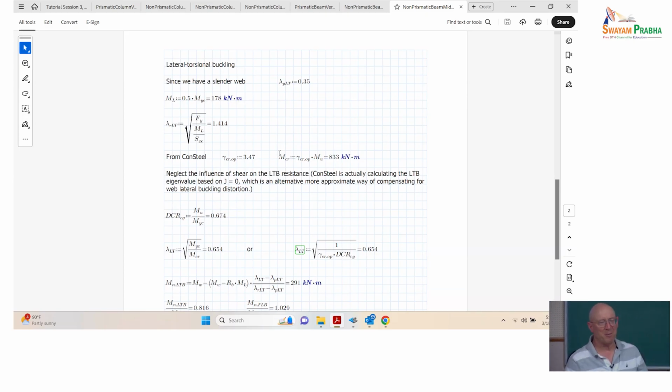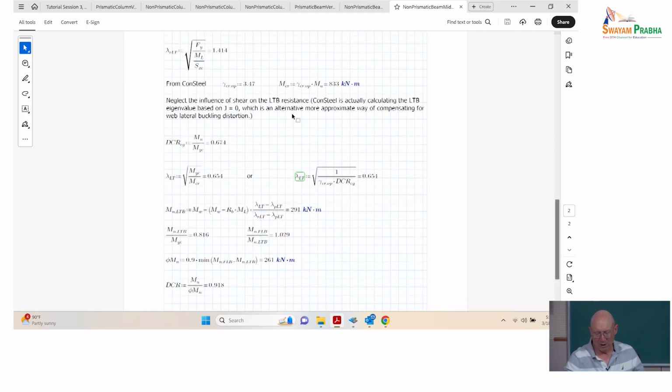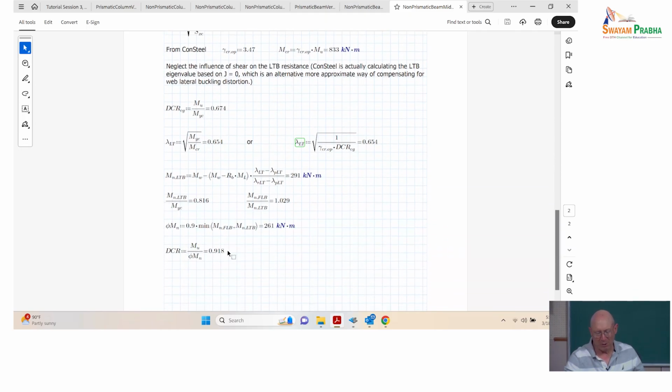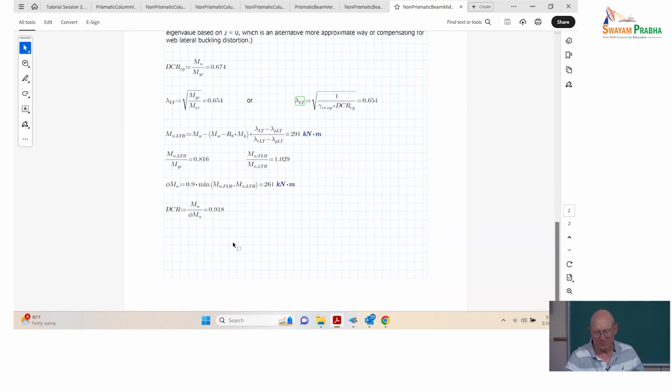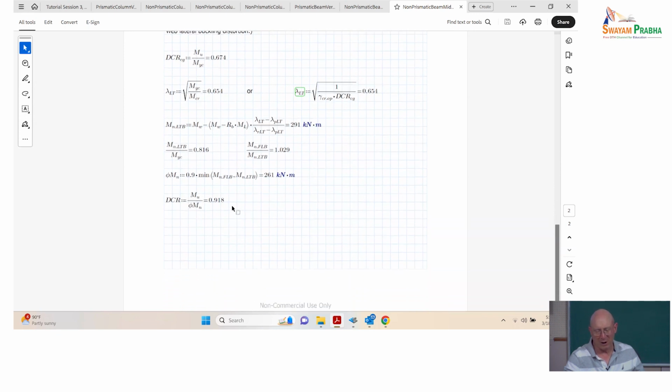Obviously, if we go at the bottom, the moment is 0 at the bottom, so there's no need to check the bottom, right? So that's all this is doing. Oh, I get 0.918 here at this section. Now, oh, okay, I know why I didn't. So when we do the calculations in Consteel, if we were just checking moment, we look for where is Mu over phi Mw largest?